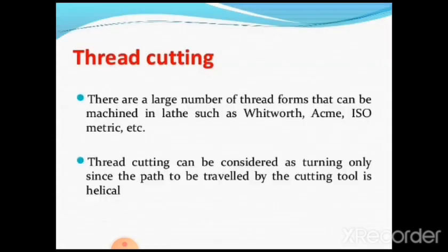So let me start with the meaning of thread cutting. There are a large number of thread forms that can be machined in a lathe. Depending upon the profile, the formation and angle of the threads has been defined at international and national levels, like Whitworth threads, Acme threads, or ISO metric threads.